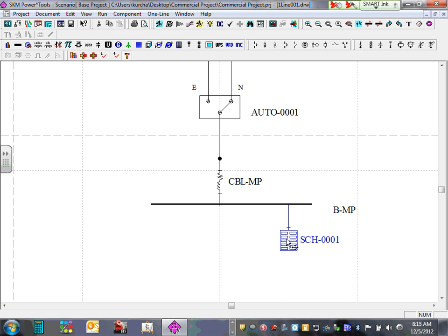So then you can go right in here, and what this will give you, Kerry, is a schedule to put your branch circuit in this panel. Thumbs up, Chad? That's all. Do I need a cable for it? No, because it's just a symbol to allow me to put my branch circuits. That's all it does. If I don't care about branch circuits, by the way, I don't need to even use it. Okay, everybody put the schedule.